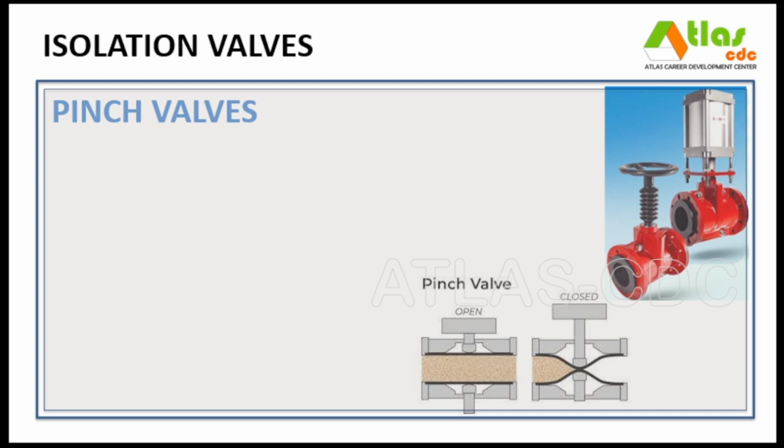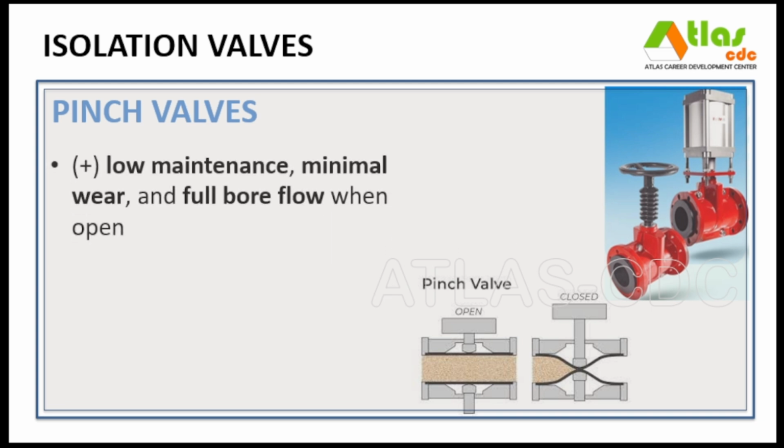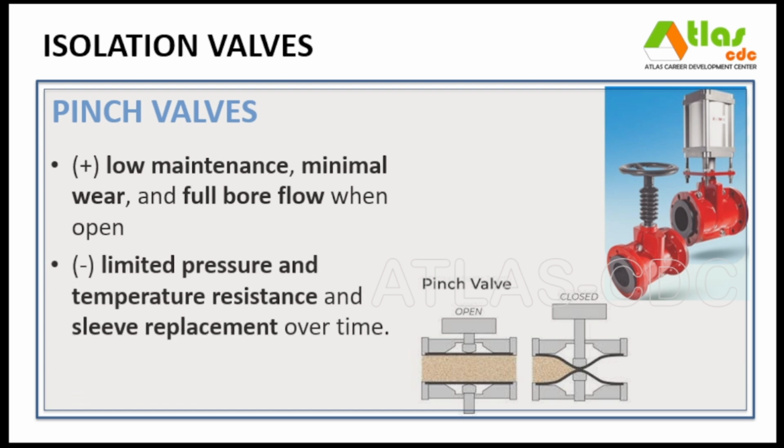The advantages include low maintenance, minimal wear, and full bore flow when open. The main disadvantages are limited pressure and temperature resistance and sleeve replacement over time. They are typically used in wastewater treatment, mining, pulp and paper, and chemical processing, where cleanliness and media isolation are critical.